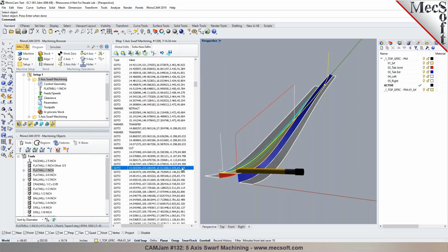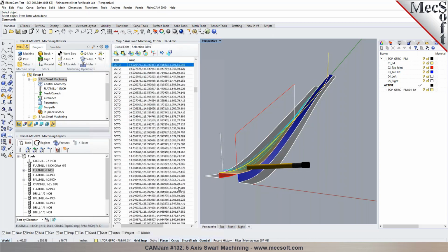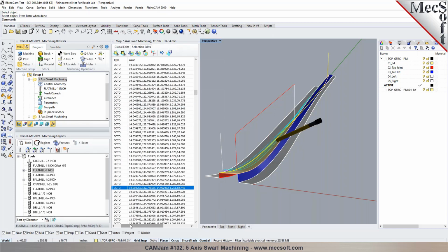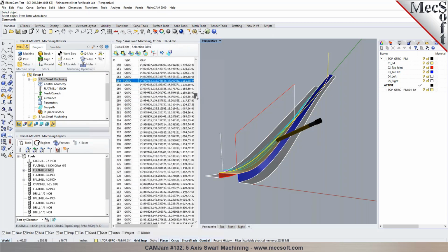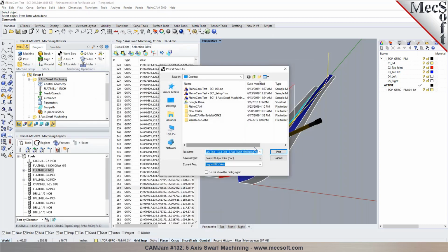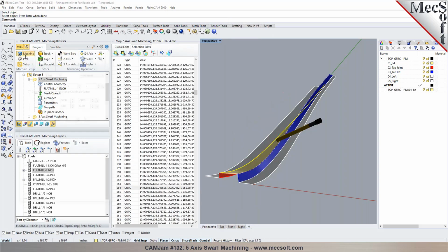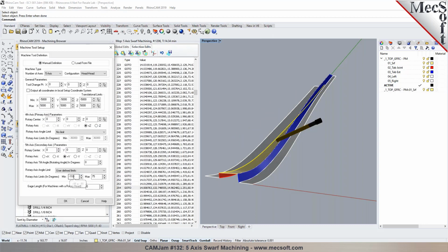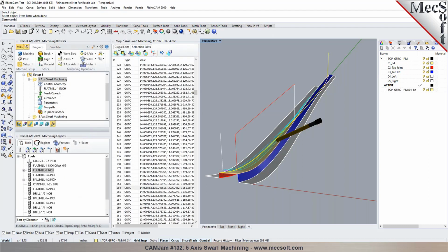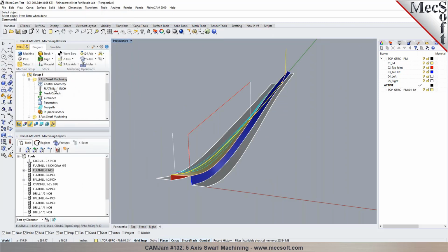But if the computed angles are still outside of the rotary axis limits, then it's going to flag and mark those in the toolpath editor, and it'll notify you when you're post-processing that machine angles are violated in the output. In this case, it is still able to find a solution, and when you post, it'll notify you about it. Okay, got it. So you can establish that as well. There are some checks built in. We do not set the limits for the work envelope, the X, Y, and Z, but we do check the rotary axis limits.